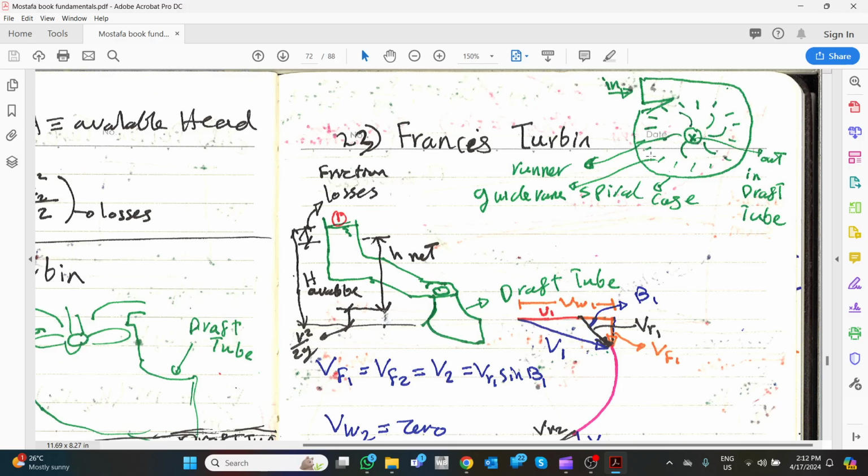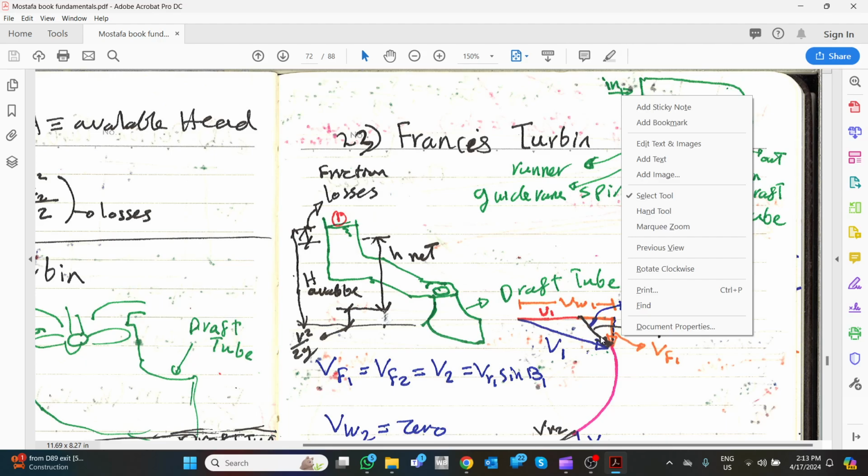So we know that velocity is going to hit the impeller, and the relative velocity is with the same curvature of the impeller, same as what we discussed before. So the whirling velocity is u. This one is the horizontal velocity for relative velocity, and this is the flow velocity. Very simple, like before.